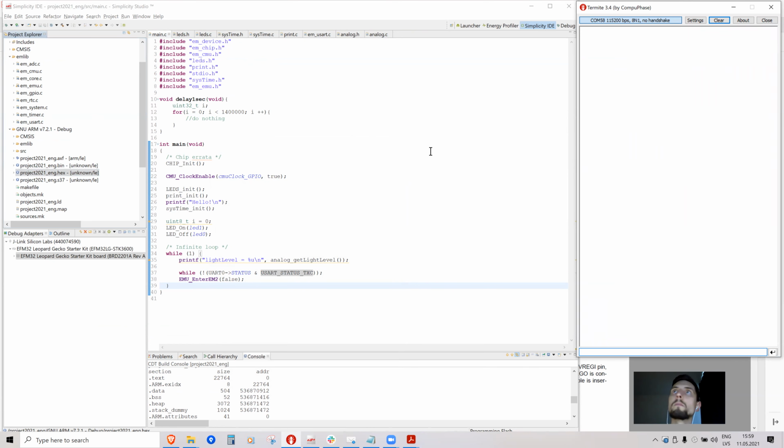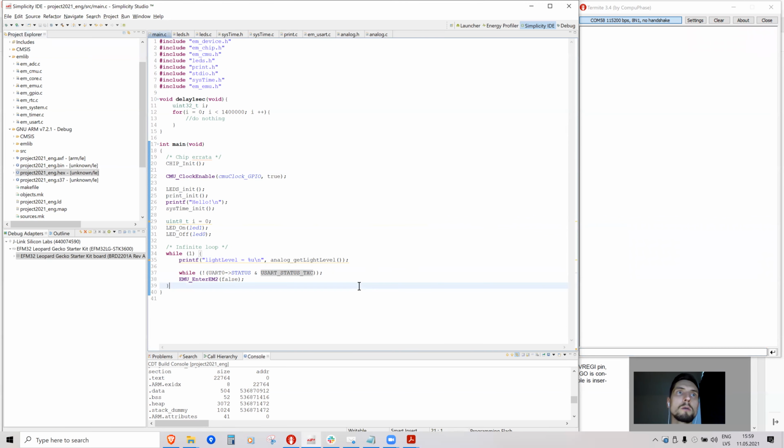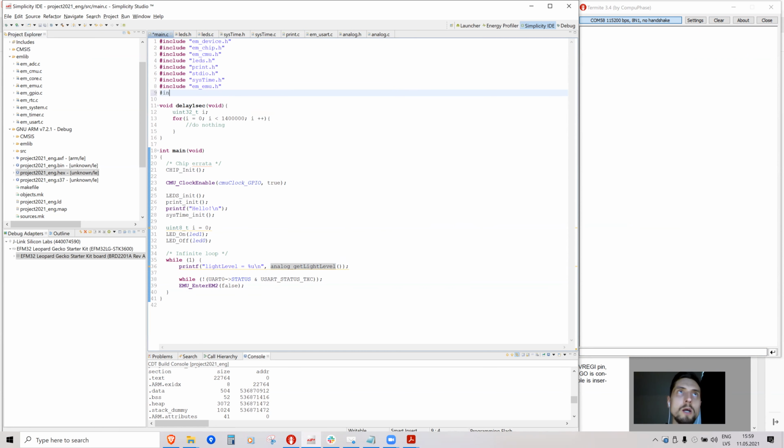Okay, do we get some information here? Looks like it's not working. Oh yeah, we need to initialize the analog to digital converter. I keep forgetting it. So first of all, hashtag include, double quotes. You see our code asks for analog to digital converter to sample a signal, but since it's not switched on and it's not enabled, this thing just hangs in this place.